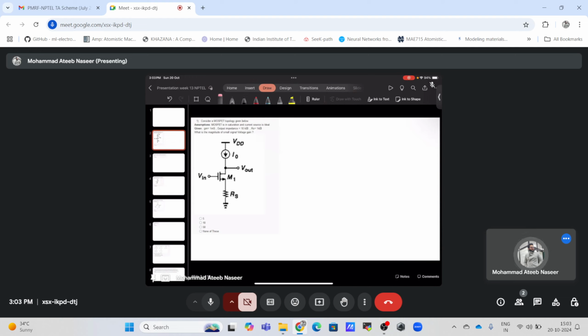We saw how the small signal model can be obtained for any two-port network, where we used a black box representation and went through the Taylor series expansion of that function and said that we want the amplifier to operate in the linear region. Those were the assumptions for the small signal model that we obtained for the two-port network.